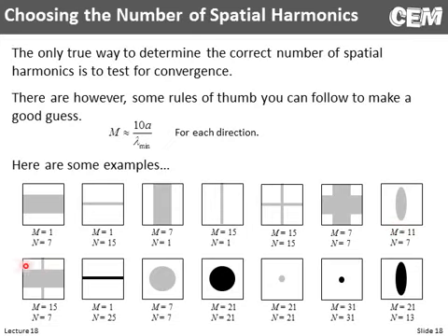So in the horizontal direction, we have this really thin bar. We need high spatial harmonics. Thick bar, vertical direction, 7 harmonics. Now if we go to really high index contrast, it's still uniform in the horizontal direction. We only need one spatial harmonic. But because it's high contrast and a narrow bar, now we probably need even more spatial harmonics in the vertical direction.